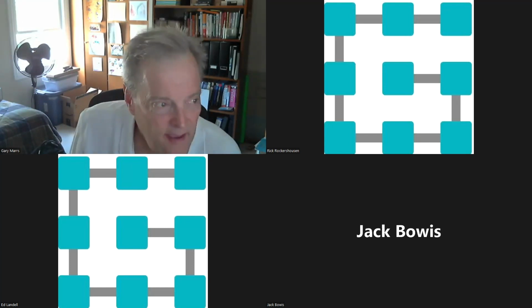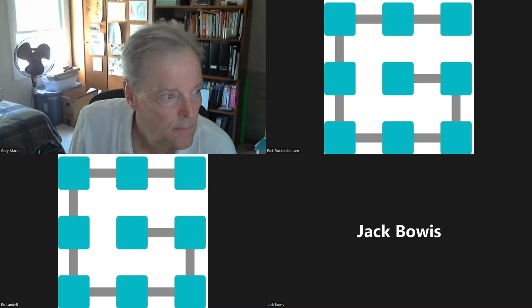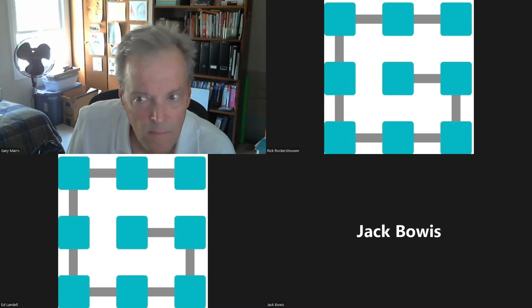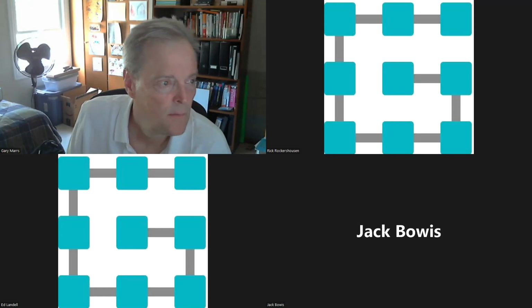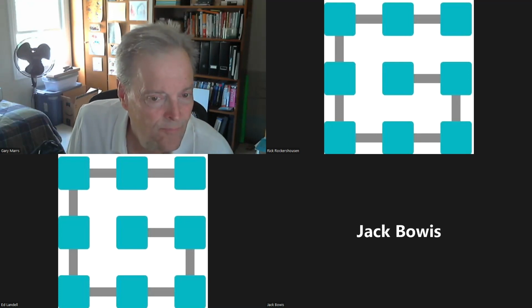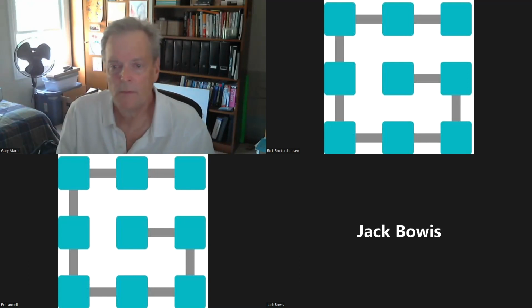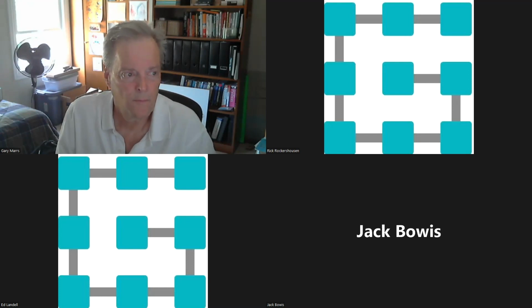Is there CAN FD on this network? Yes, I think so. Is the specific difference between CAN FD and CAN that it's extended, or is there a different difference that I'm not aware of? Yeah, normal CAN frames have 8 bytes of payload, and with CAN FD, the bus actually speeds up during the transmission of the payload of the CAN packet.